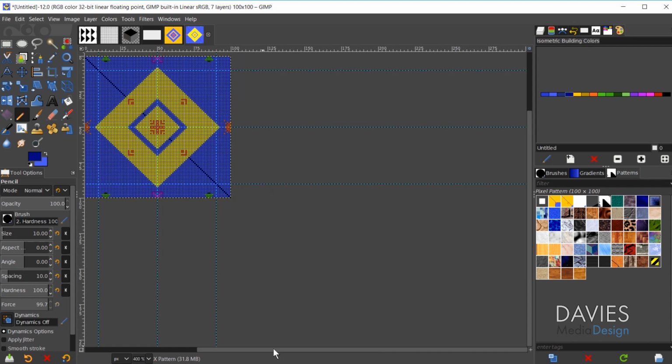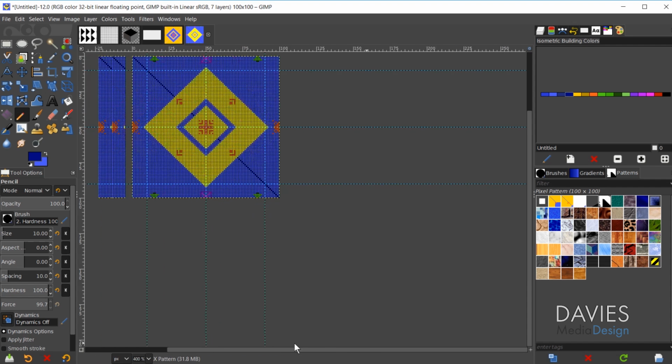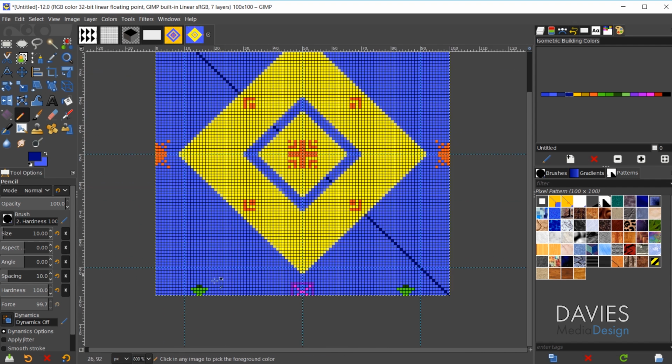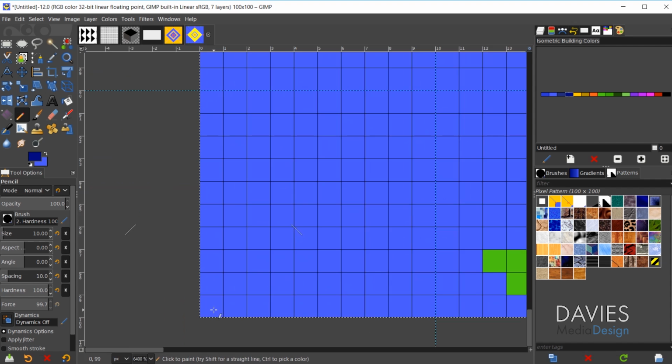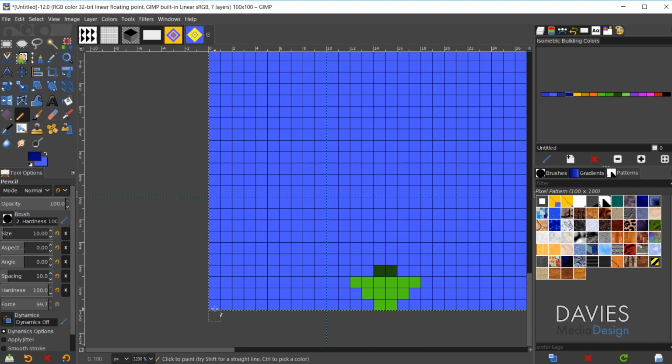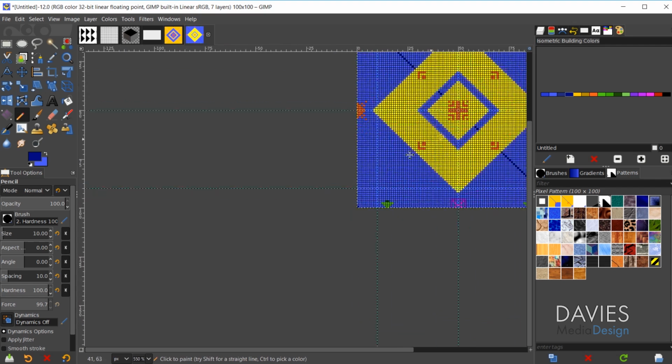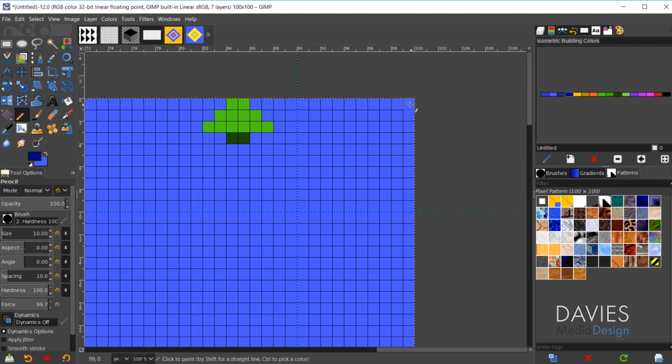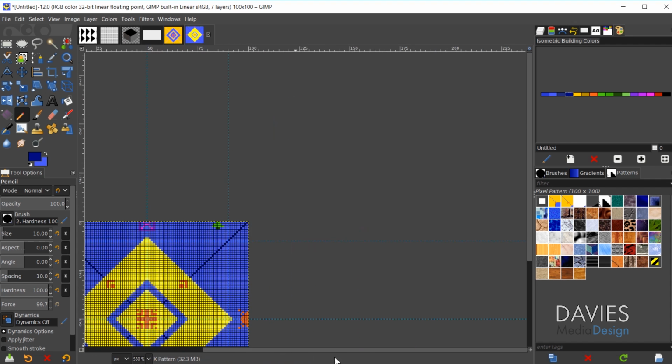And that should draw a nice straight line through your entire design, creating that X. And now we can do the same thing over here, so hold Control and zoom in with the mouse wheel, not too much, so right there. And so I clicked once and hold Control, zoom out, move over to this side of my design, hold the Shift key, click, and now we have that X there.